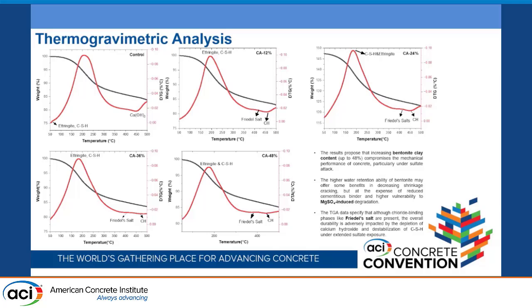Thermogravimetric analysis also showed that chloride-binding phases like Friedel's salt were noticed, but overall we noticed an impact on the overall durability of the concrete, as a depletion of calcium hydroxide and destabilization of the CSH under extended sulfate attack.